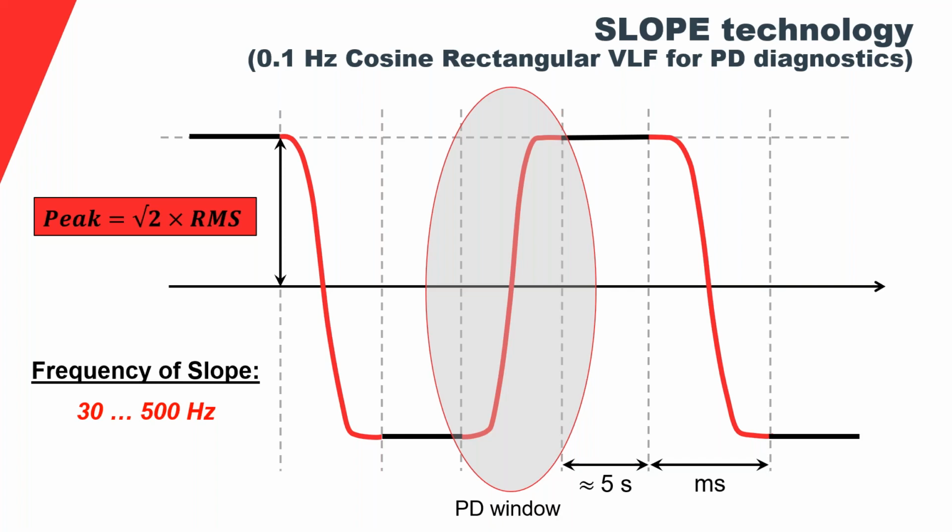We've never tried that. It should work because it has the polarity reversal at power frequency, at the same slope as 50 and 60 hertz. But we have to test it. So there was a lot of field trials, studies, investigations done, and pretty much 2008, 2010, it was proven to be equivalent to damped AC and as such equivalent to power frequency. So you will get results similar to power frequency when you use this waveform as well.